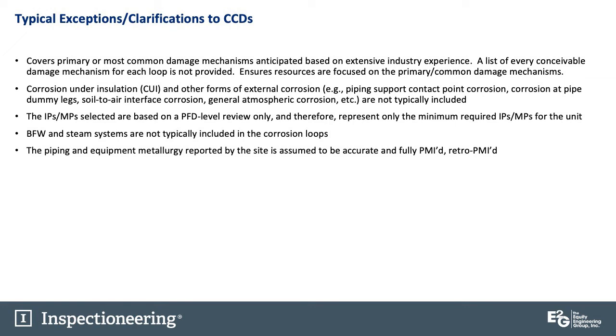So you do want experienced SMEs, whether they're in-house SMEs or external, leading your CCD development, because you want that level of experience, and you want to make sure people you use for this have good knowledge of what the primary and most common damage mechanisms are, what the biggest risks are going to be for each particular loop in a refinery unit.